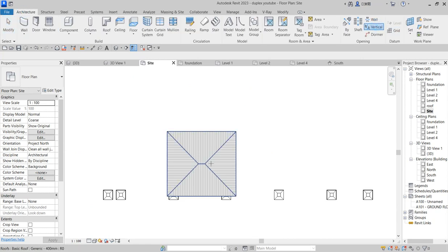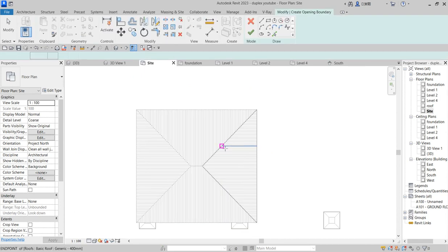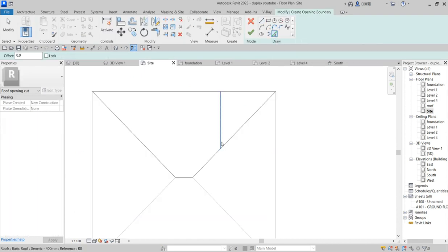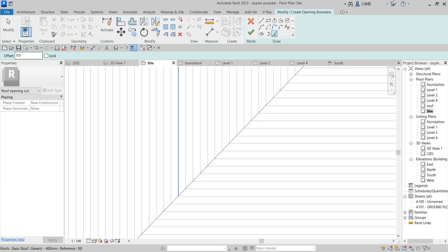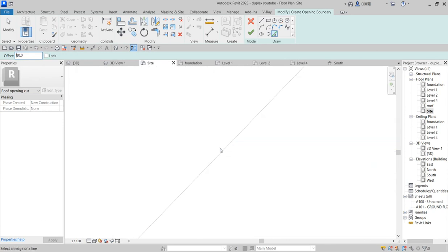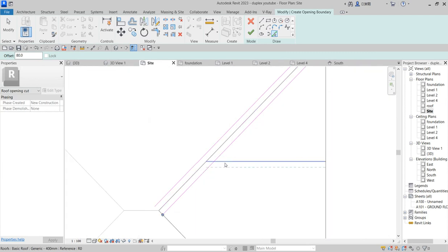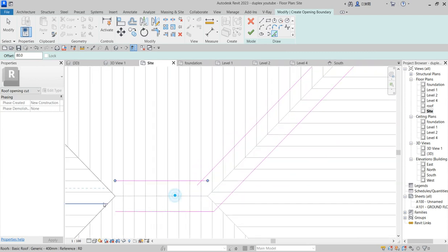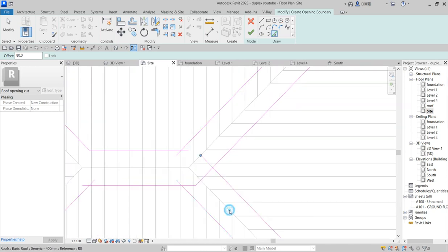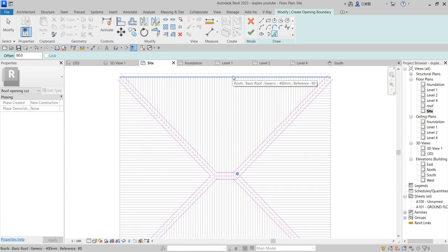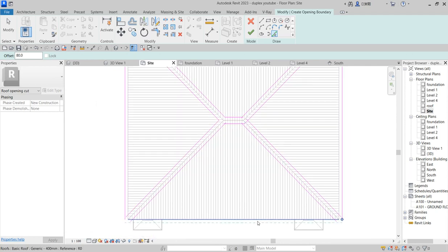architecture, click on vertical, because you want to create this particular roof gap. So as you select the roof, then click on the line and you start doing it. Now set the line from the roof where that space you want to cut out. So you do that to select the vertical area. So as you have done this, click around, and at the same time click around. So trim to get the detail accurate.